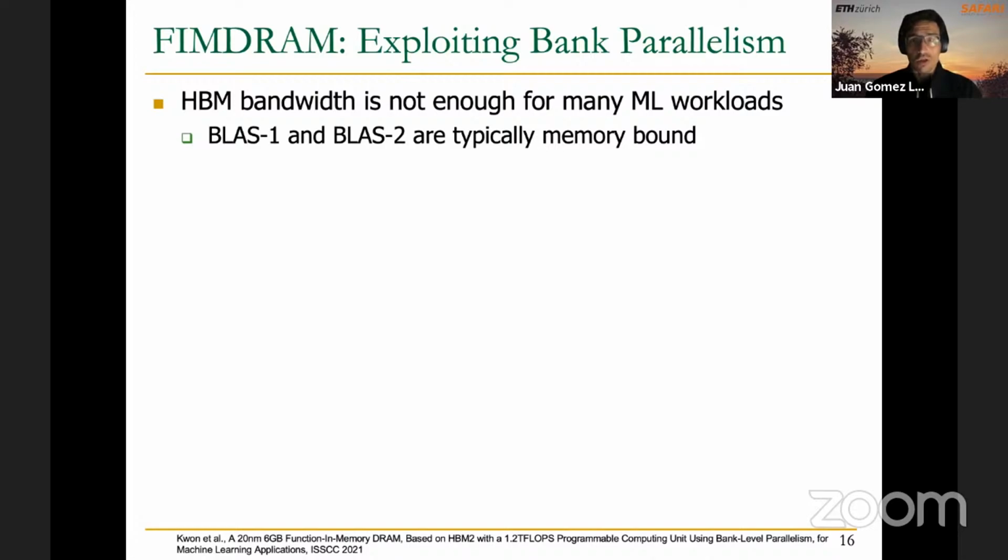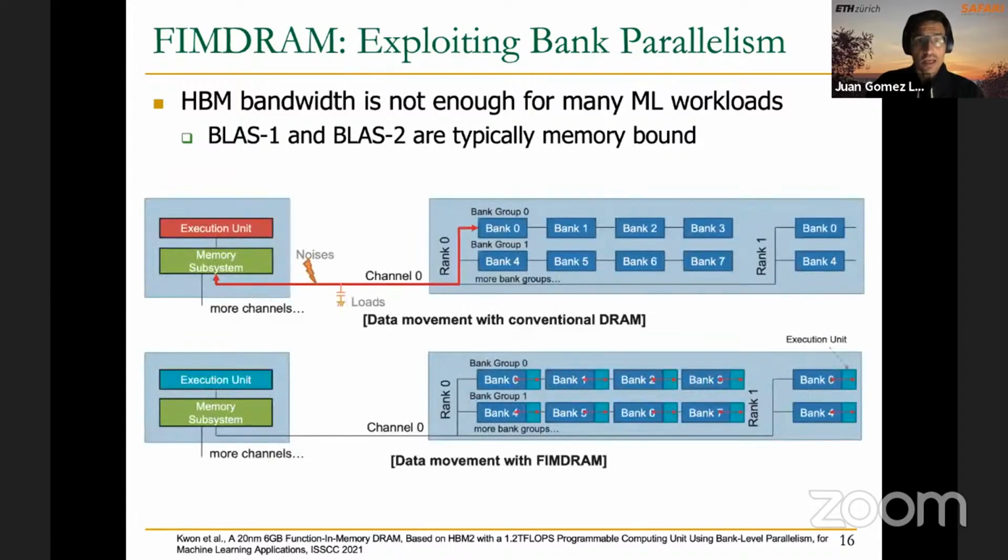And if we focus on linear algebra workloads like BLAS routines, we will see that most level 1 and level 2 routines in BLAS are memory-bound. Only BLAS level 3 has much more data reuse, and those routines are typically compute-bound, as you may know. So for this type of ML workload, and these patterns are very frequent, for example, in machine learning inference, it's desirable to provide the processing elements with higher bandwidth.